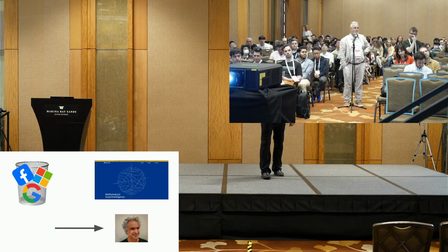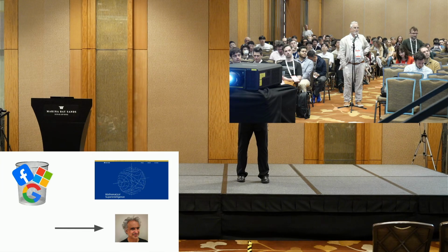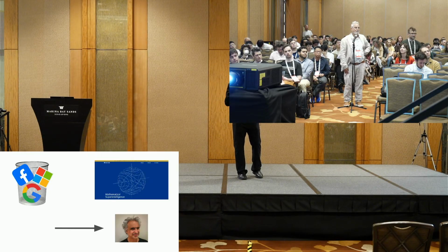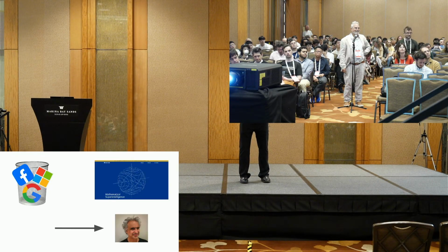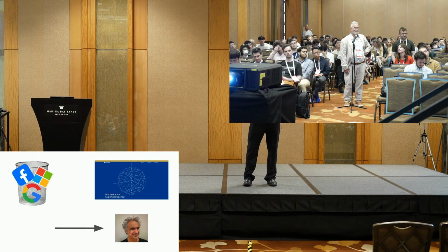So when I worked at my last company, Groq, there was a situation where somebody had used a struct as a type on the interface of a module, because these signals were grouped together logically, so you should have a struct. And then in code review, that got rejected, because lots of hardware design engineers hate a struct. They don't know what that means. How are the wires laid out? Will some inefficiency be introduced? And the person who wrote that code had to delete the struct and replace it with the individual wires that made it up. Right, that was this year. This was not in the past.